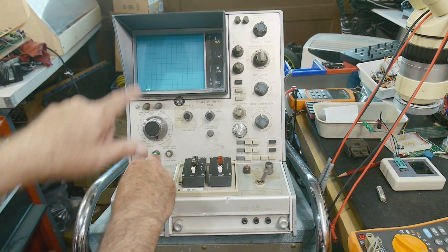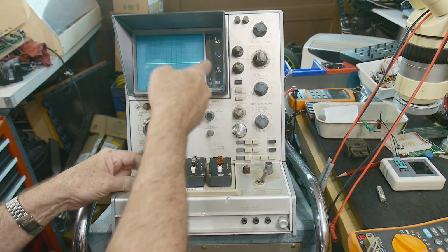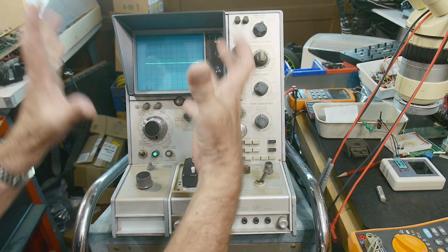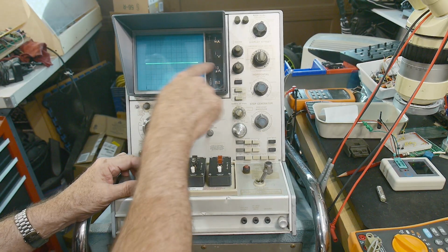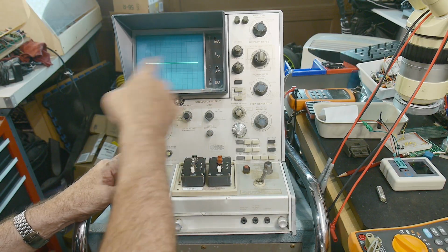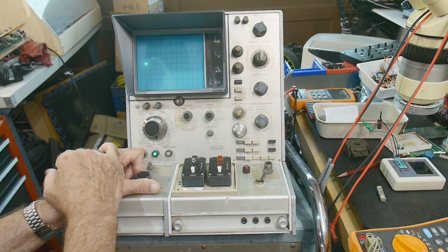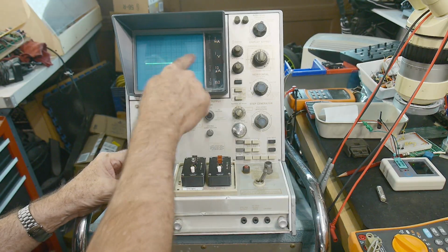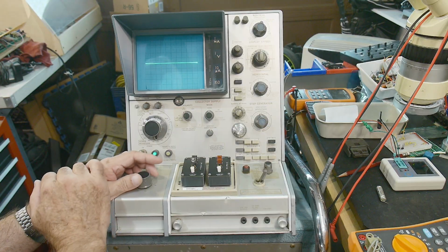Is that on camera? Maybe it's kind of way down there. I can move the spot up so you can watch it. So now it's drawing a line, and that line is because it's sweeping back and forth, and the phosphor of the CRT lets you see it all the time. But it's actually going back and forth 120 times a second, okay? It's rectified AC, so it's 120 hertz that it's scanning back and forth. And it's 1 volt per division, so it's scanning back and forth, 0 volts to 1 volt, 0 volts to 5 volts, or 0 volts to 10 volts, right?